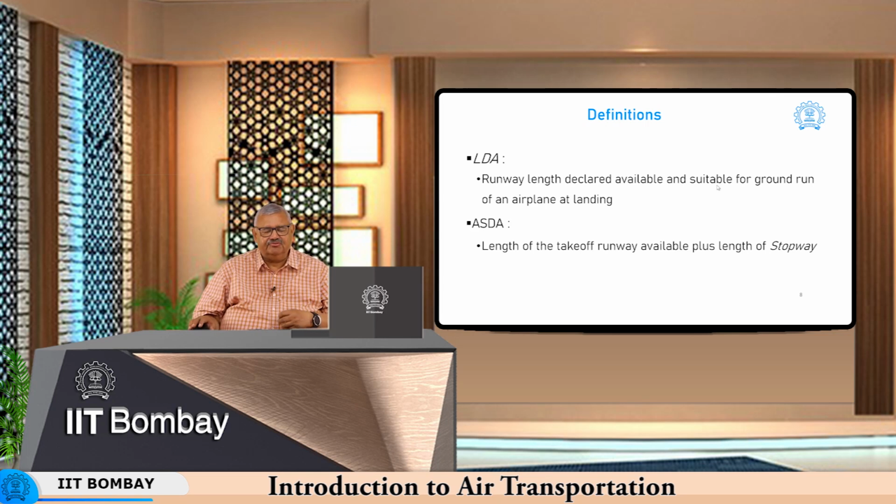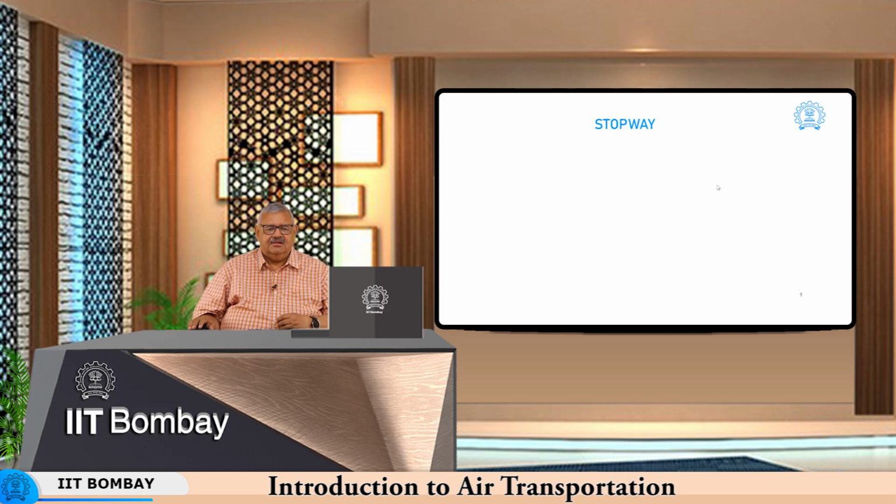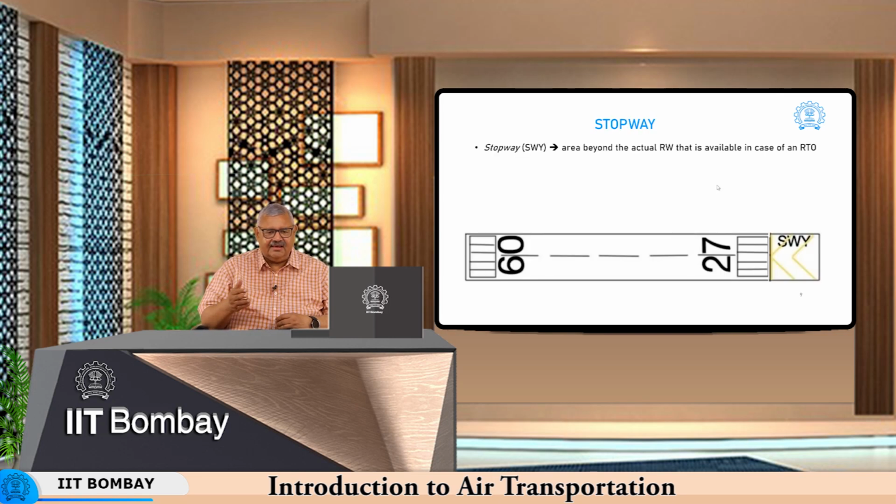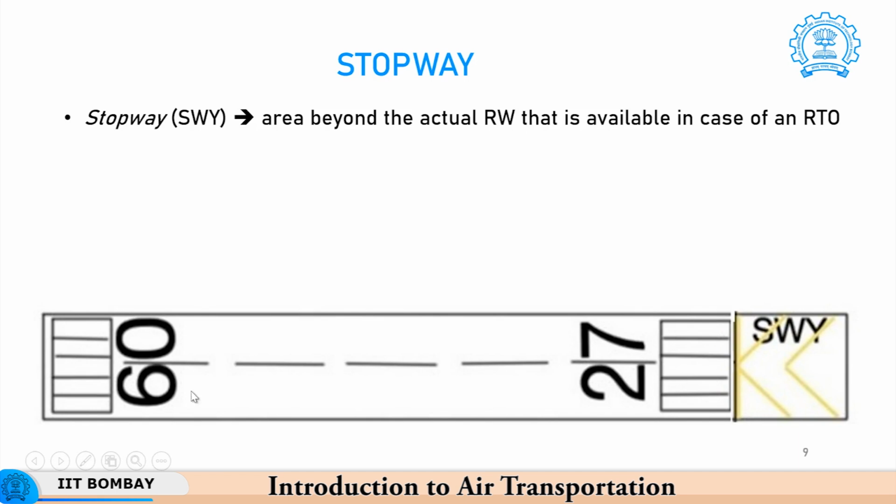So, now we have introduced a new concept called stopway. Let us understand the meaning of that. Stopway is basically an area beyond the actual runway that is available to stop the aircraft in case of a rejected takeoff. So, once again, at the end of the 09/27 runway, when you come from 09 and you